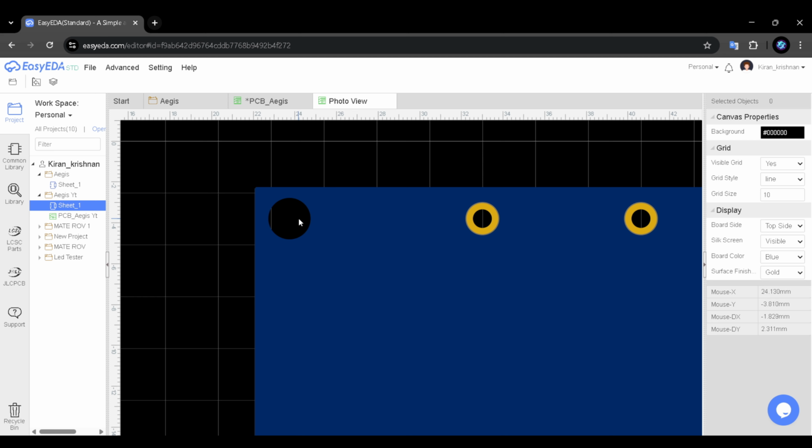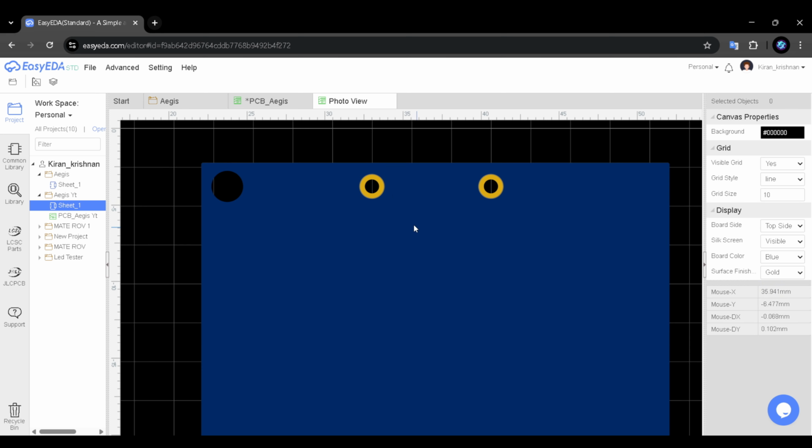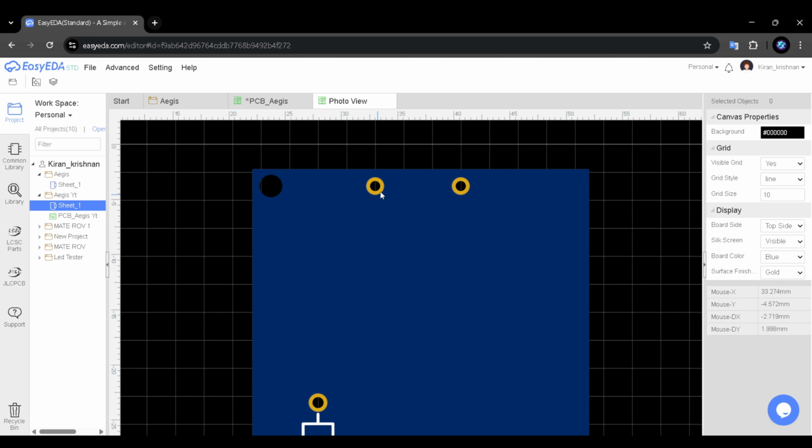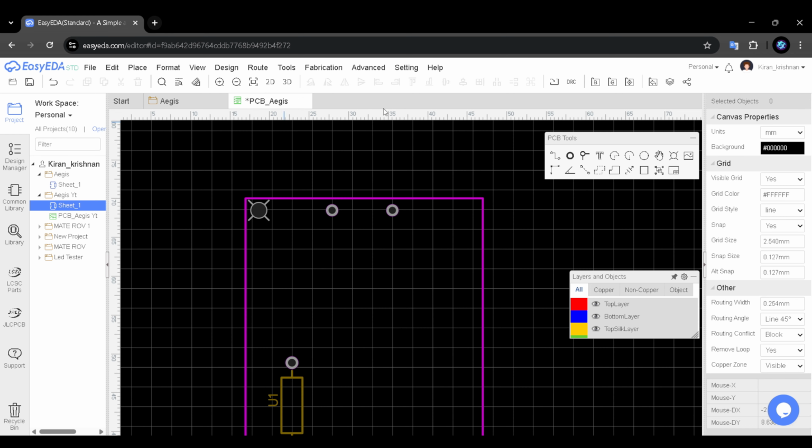So that means that basically it wouldn't conduct. So here, as we're using a through hole LED, we're going to test LEDs, right? So this got to be conductive for it to work. So for that, we're going to use a pad over here. And let me remove this. So these are basically used to screw down PCBs onto mounted structures and stuff.